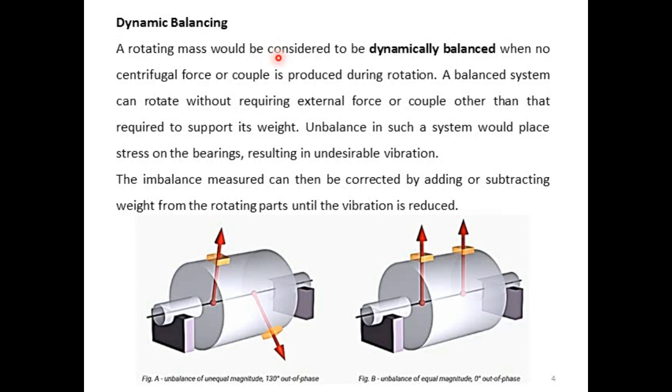And because of this rotation, if there is some unbalanced force in a system, it will create vibration, and because of the vibration there will be a counter effect on the bearings which are supporting the shaft, and also the shaft will get damaged.